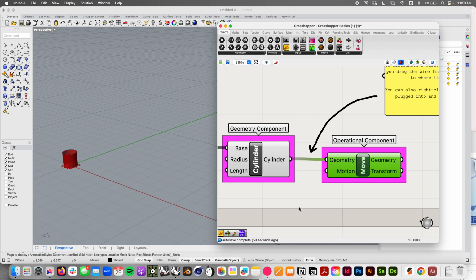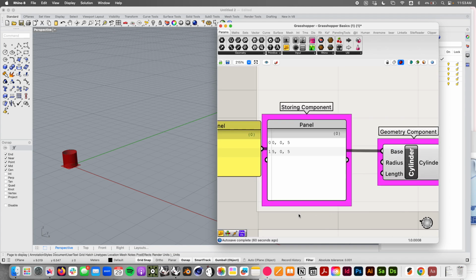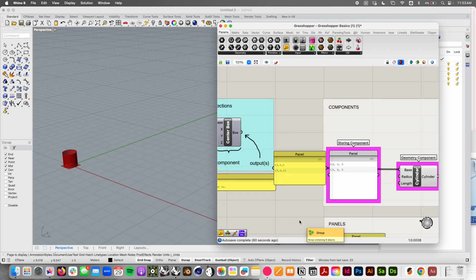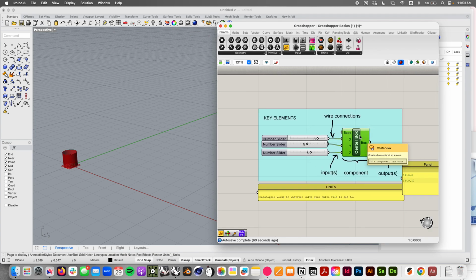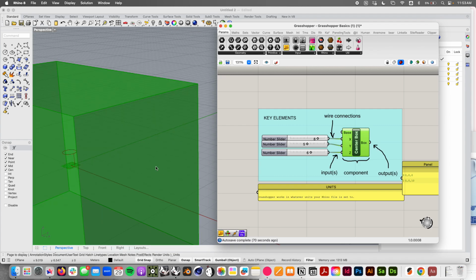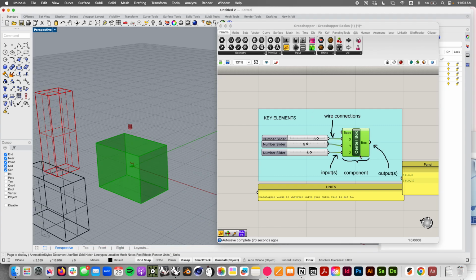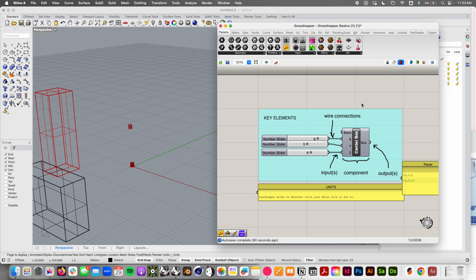Oh, yeah, getting rid of the big shaded box in Rhino. That came earlier on. In our initial explorations, we were playing around with this center box component. And that one by default is going to be turned on, previewed on. It'll look something like this. If you want to turn it off, you don't want to see it in Rhino anymore, you can right click on that component and uncheck where it says preview. So we're going to preview off that component. It should disappear inside of Rhino.